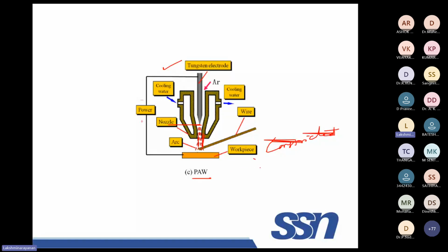In the case of gas tungsten arc welding, your arc will be a diverged arc, where your heat source is spread across a larger area. In the case of plasma, your arc will be a parallel beam where a smaller area is focused. That is the advantage of plasma: rapid heating and cooling. That helps give low heat input for our system.